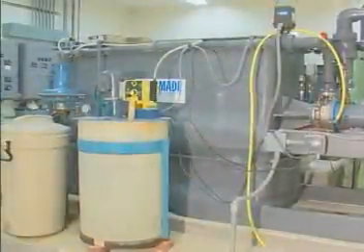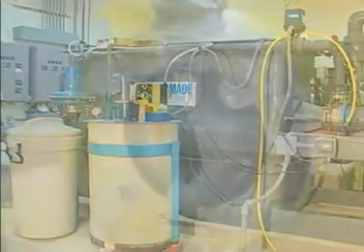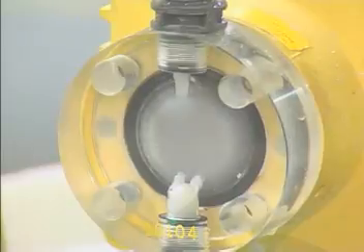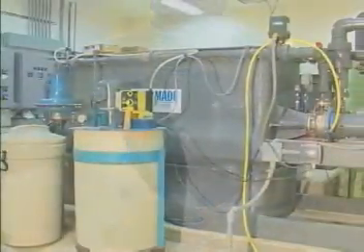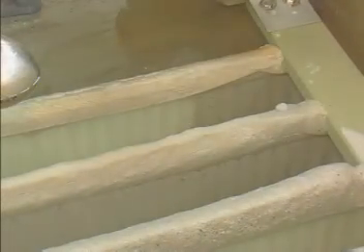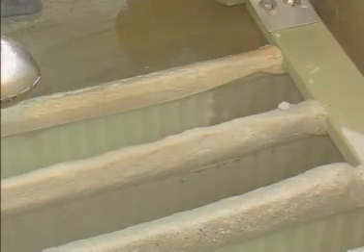To offset the rate of increase on the head loss, a constant supply of new DE, known as body feed, is added to the water. This body feed extends the runtime of the filters between cleanings to maximize the amount of water processed before filters reach their design head loss and require cleaning.